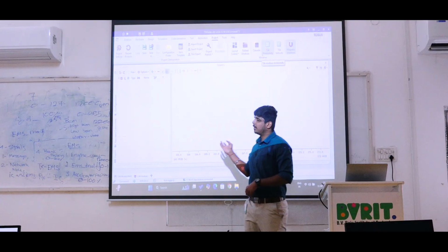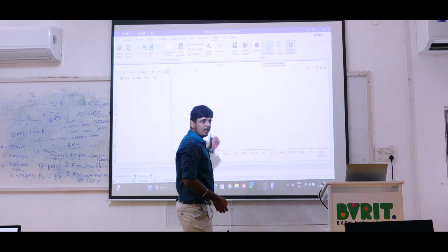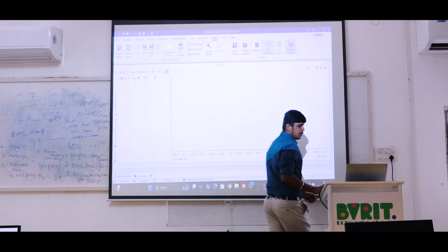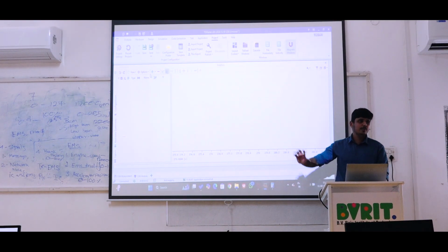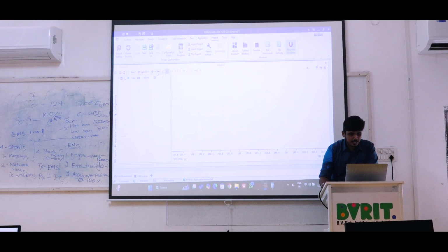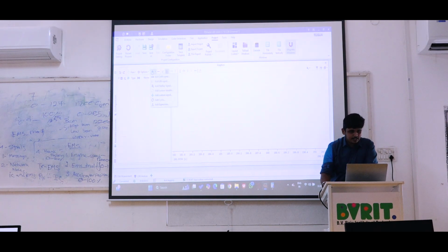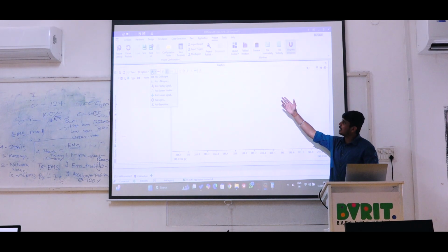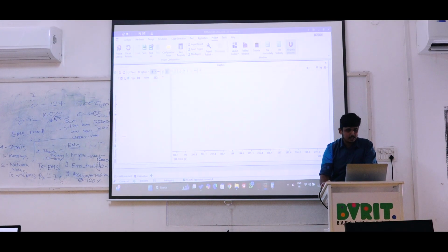Whatever signal we are transmitting, we can see as a graphical view. Now for example, here is how we can add the graph signals. For that we have the plus option there. Once you click, you can add a CAN signal, signal in signal, or flexible signal. Now we are using the CAN signal. Just add CAN signal.